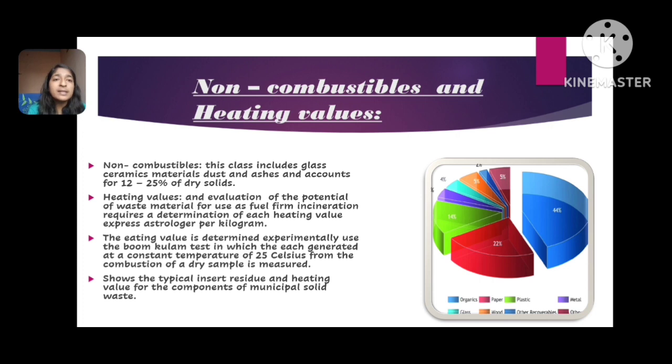The non-combustibles. This class includes glass, metals, dust and ashes, and accounts for 12 to 25% as dry solids. The heating value. An evaluation of the potential of the waste material for use as a fuel for incineration requires a determination of its heating value. It is expressed in kilojoules per kilogram. It shows the typical range of heating values for the components of municipal solid waste.